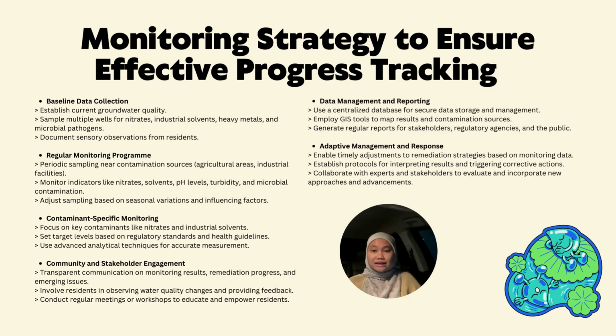So the next slide is about the monitoring strategy to ensure effective progress tracking, which is baseline data collection to establish current groundwater quality, and sampling multiple wells for nitrates, industrial solvents, heavy metals and microbial pathogens. Document sensory observations from residents.